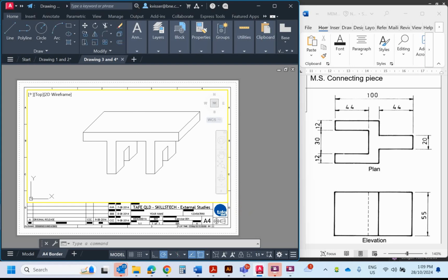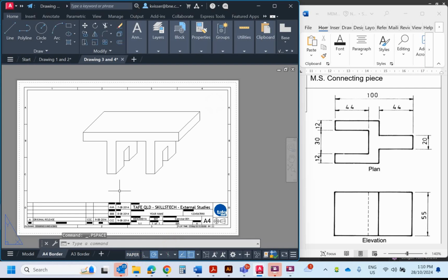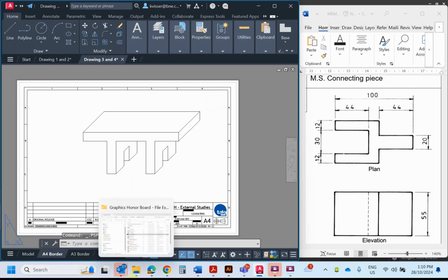So you're going to need one sheet there for that. And then you would also need another sheet for your other one. So also just remember, once you've got your scale 1:1, just lock it in place and then double click out of it, and that gets you into your paper space, and that's where we do our annotating.